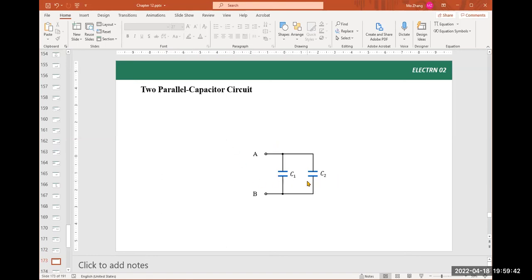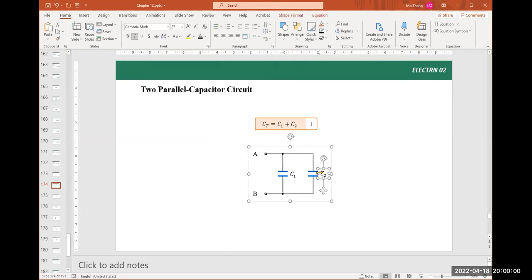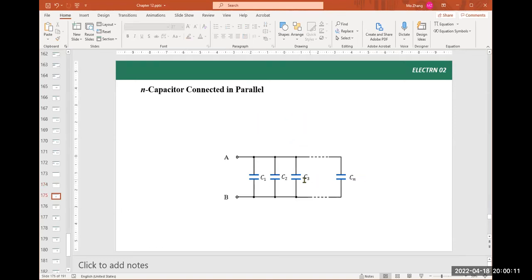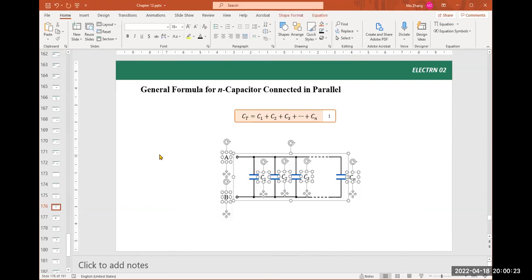If we put capacitors in parallel, we actually improve the total capacitance. And I think as most members have guessed the formula, the total capacitance is simply adding them up. The total capacitance is the sum of individual capacitances. In other words, the total capacitance is C1 plus C2 plus perhaps more capacitors, C3, all the way to Cn. So this is how we find the total capacitance. Easy, this is easy if you place capacitors in parallel.